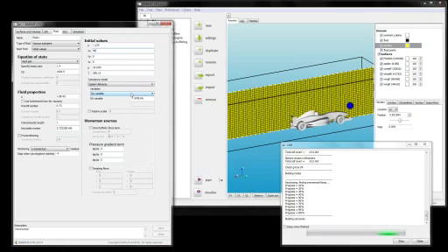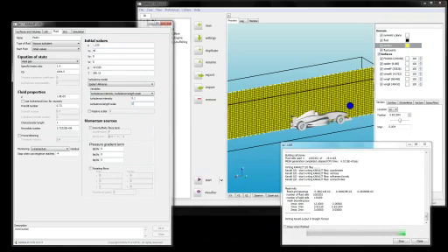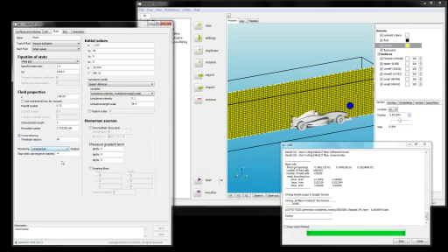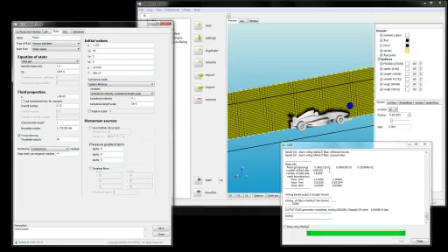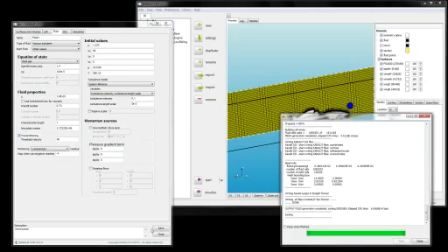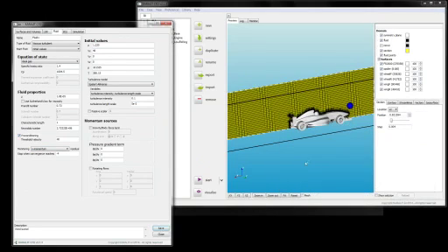I'm going to use the SA model, with a turbulence intensity of 10% and a length scale of perhaps 5 millimeters. I'm going to turn preconditioning on because this is a density-based solver and it needs preconditioning when there is a very small degree of compressibility or no compressibility. That's it in terms of setting up the fluid panel, essentially the flow conditions.